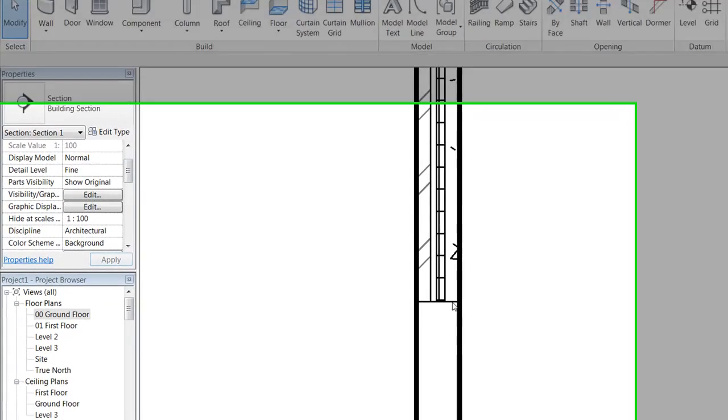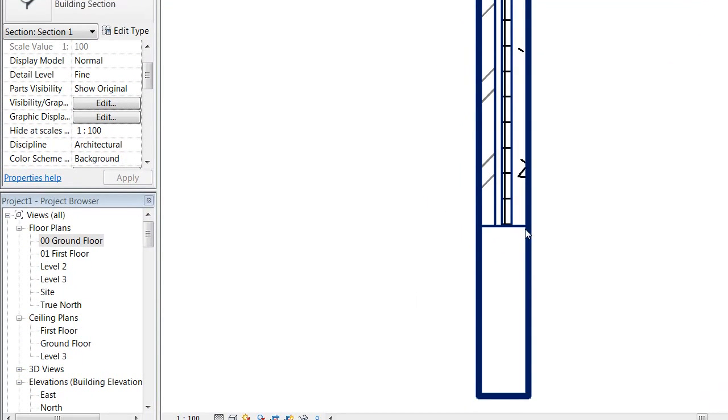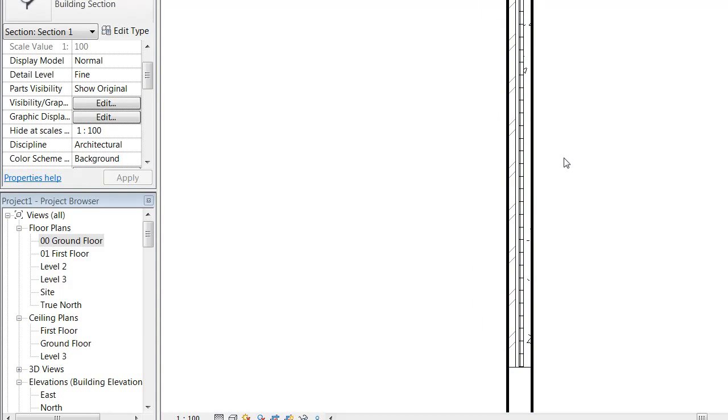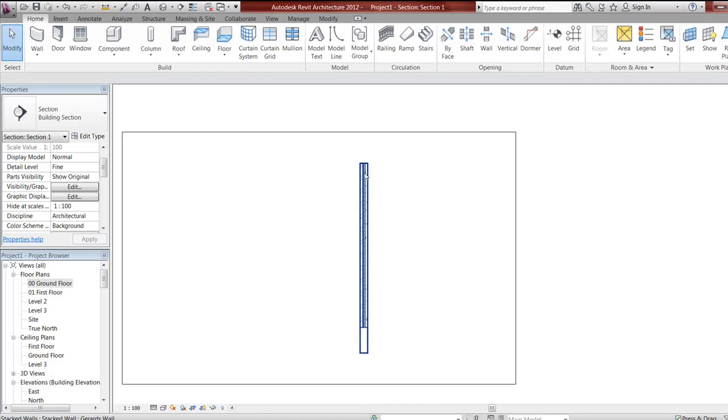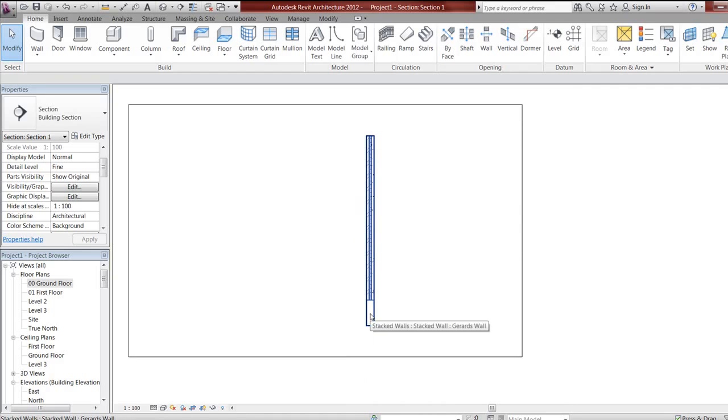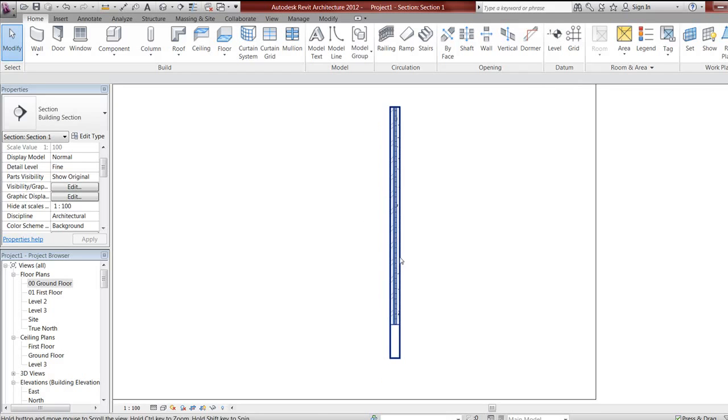That gives you height, and then you set the actual inside. You go 1000, and then if you did another wall, you put that height, and then the actual height will be variable because that's the actual height you want the wall. So then you go up from that. So your last wall will always be between the 1000 and the height. So minus the 1000 from the height, and that's it. So that's how you do stacked walls.